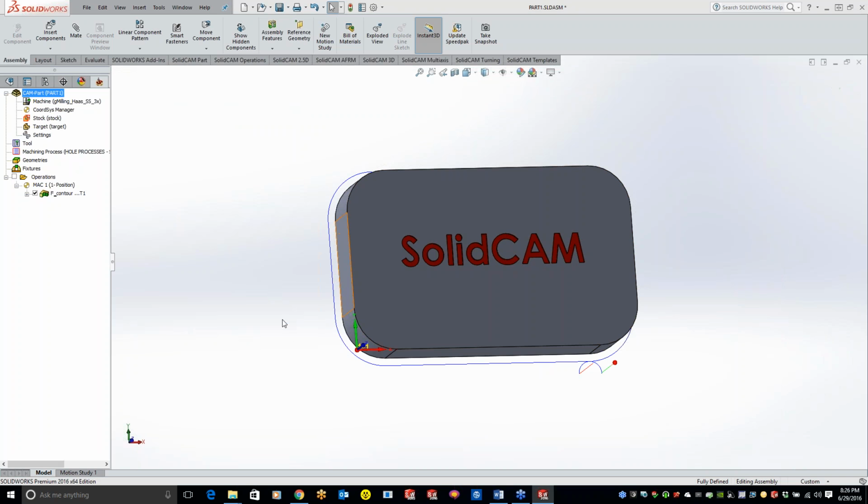Right here, it'll pop up saying design model replaced. Do you want to continue? And we can hit yes, and it will update to that new model, and it will relink it to the SolidCAM file. Or what you can do, like I said, if you have a family of parts, is relink it to a different SolidWorks model and keep all your toolpath there.